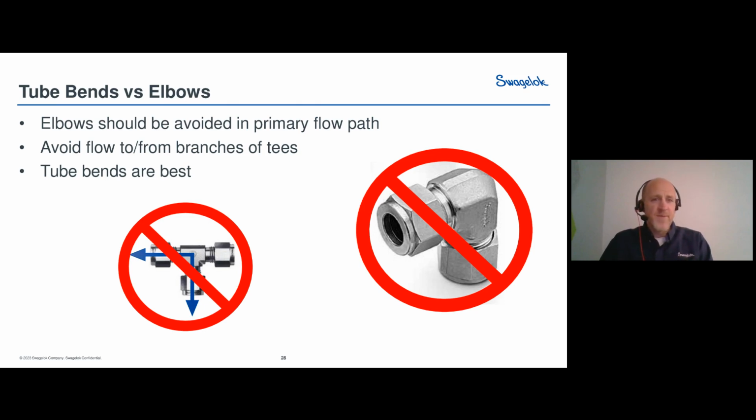All right, let's talk about some of these points. One of the things that we have to concern ourselves about, especially when we have a Plan 52, like we looked at, where we're relying on that thermosiphon effect or a pumping ring, is that we want to avoid flow restrictions wherever we can. So as a result, we're going to use relatively larger diameter tubing. Where a flush plan might use a half-inch diameter tube, one of those Plan 52s or a 53A might use 3/4 inch or maybe even 1-inch tubing, just to reduce the flow restriction. Because again, that thermosiphon effect, that pumping ring, doesn't provide you with a lot of motive force.